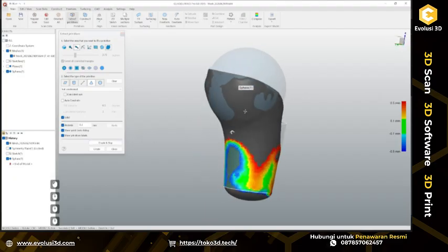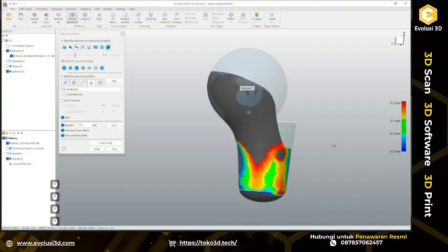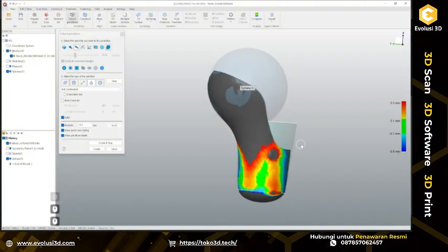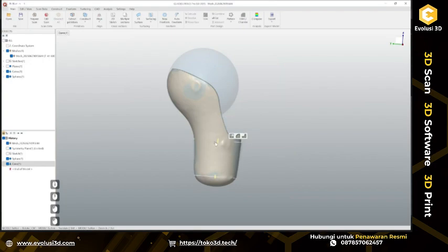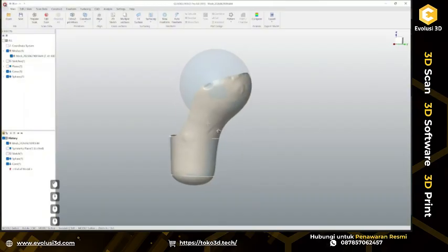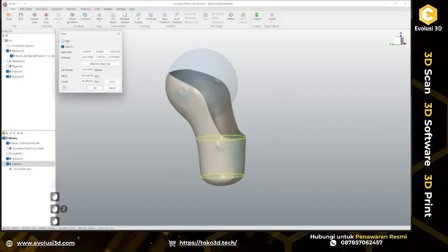Let's see analysis. Well, it kind of fits, not so great. But at this point, I want to try to use this cone just for testing, if this would actually work in such case. I'm just going to make it slightly shorter, edit this and say I don't want this to be a solid, I want just an outer wall.